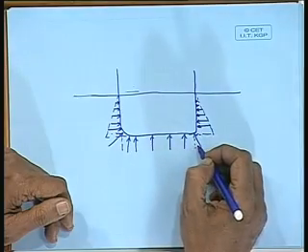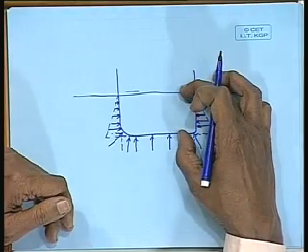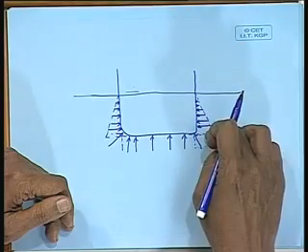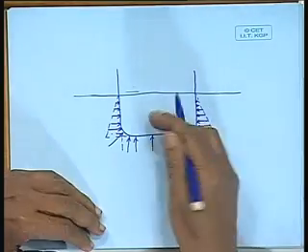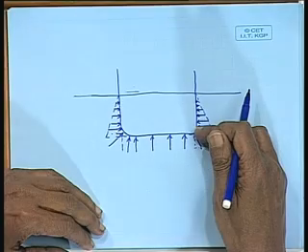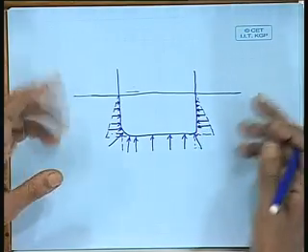So, what we are getting is a pressure which is trying to push the body up. And how much is this push? What is the pressure acting here? If it was a completely rectangular body, you can see it will be rho g h, h being the depth, and integrated over this breadth will be the total force, that is rho g into b into h, that is equal to area of the body, right, multiplied with rho g gives the weight per unit length. So, the force that is pushing the body up is equal to the mass of the water displaced.